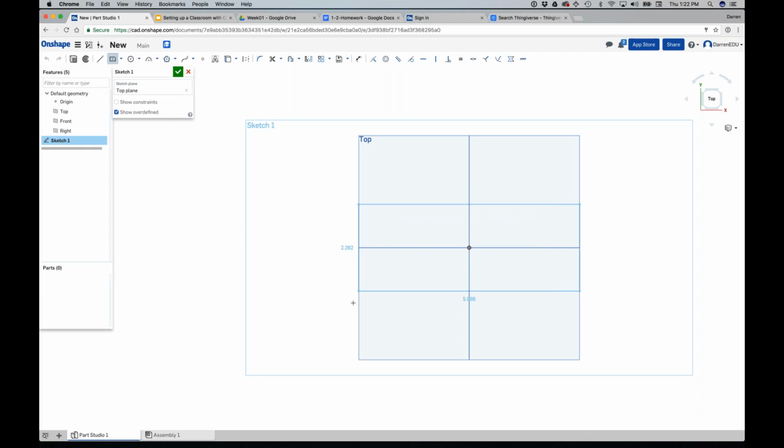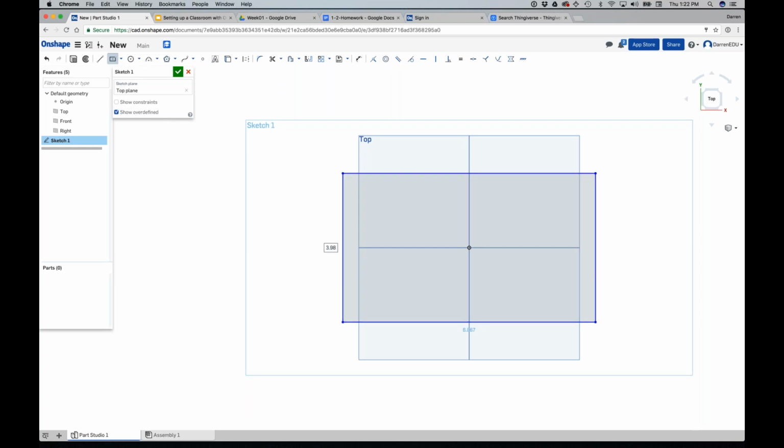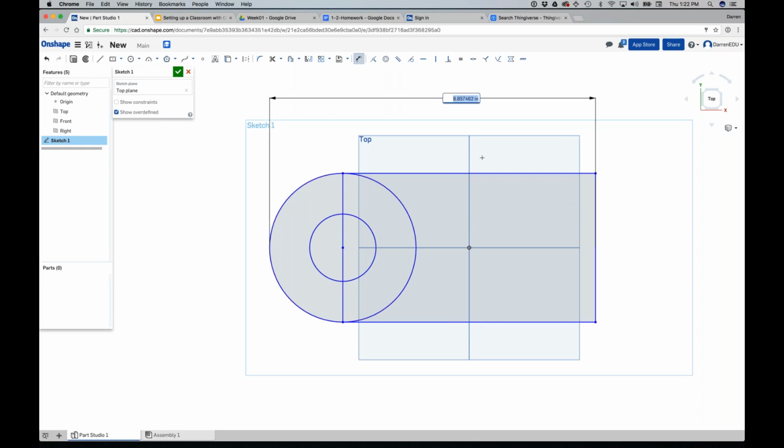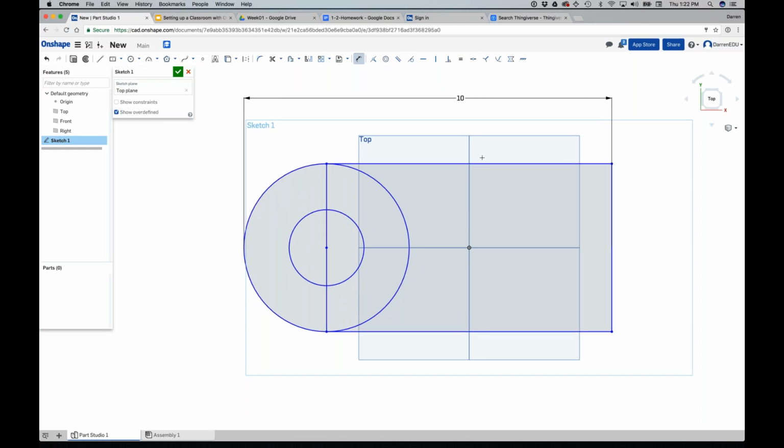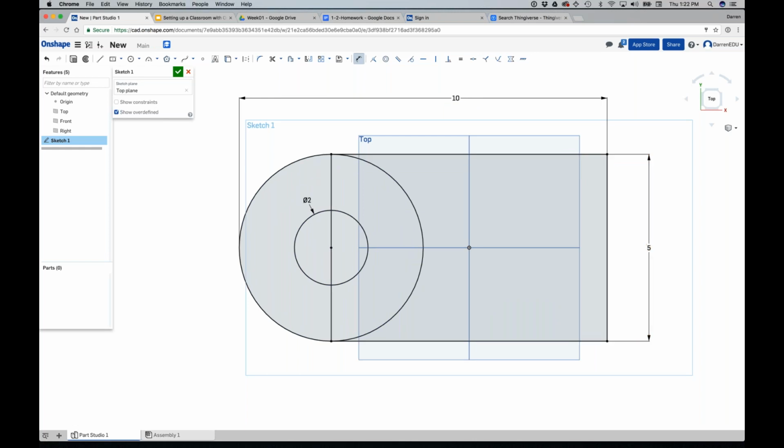If you're not familiar with 3D CAD, again, I apologize. We're not here to teach you 3D CAD in this webinar. But basically, I'll say most CAD models start with a shape. You can add dimensions to that shape to actually size it. In this case, maybe I'd like it to be 10 inches, and I apologize to our European attendees that I'm using inches. You can add other dimensions. Maybe I want this 2 inches, and I'll throw in a dimension here as well. We'll make that 5 inches. Okay, I'll hide the planes in the background so you can see what I'm doing.